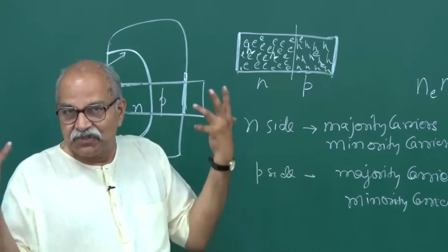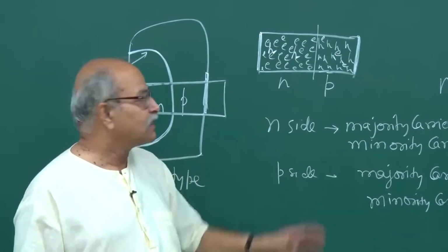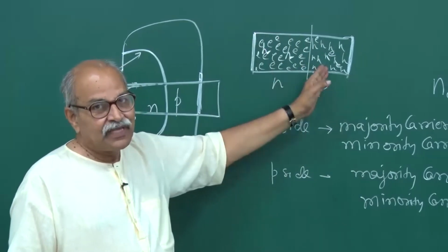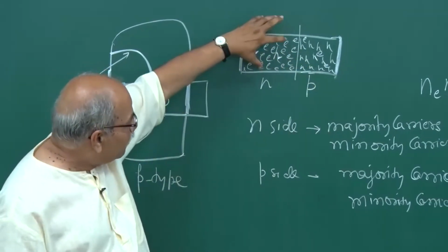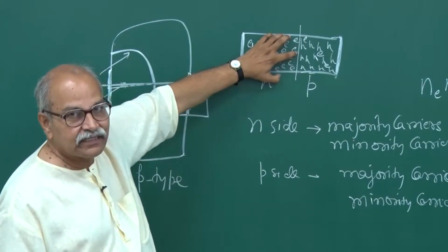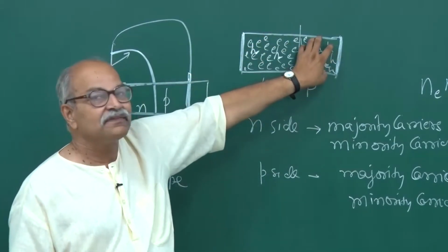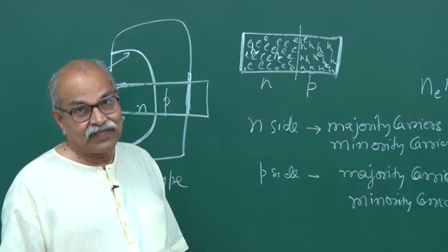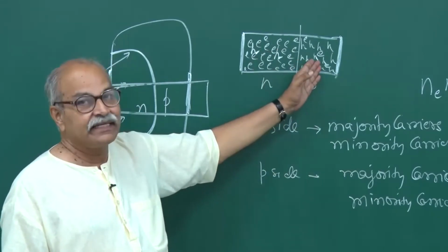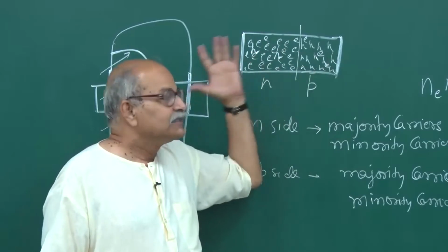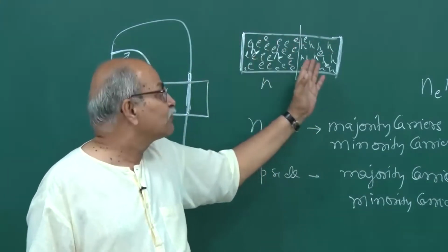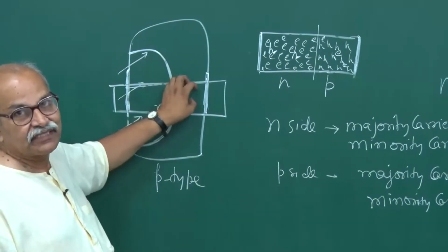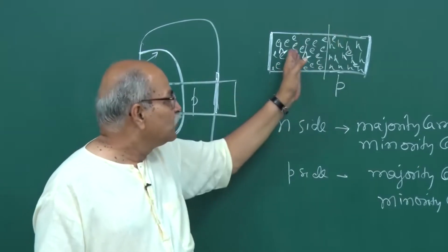So, all that usual electron movement and hole movement is allowed in this entire wafer, in this entire material, and therefore having a large concentration of electrons here and a very small concentration of electrons here is a very non-equilibrium situation. If you have such a huge concentration gradient, and if the movement is allowed, they are allowed to go from here to here. Remember, this whole thing is one single crystal on which you have done all these diffusions, and therefore that movement is allowed.